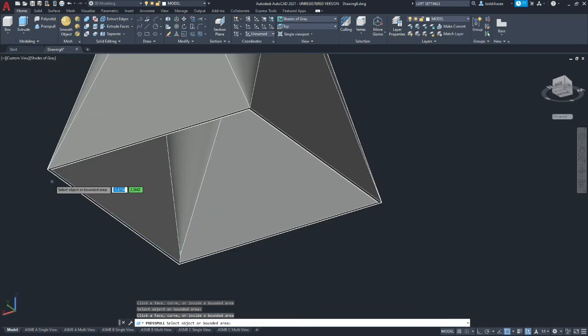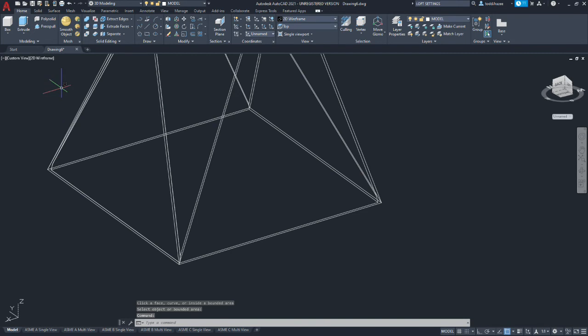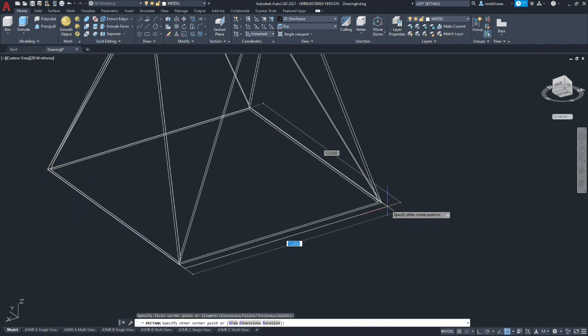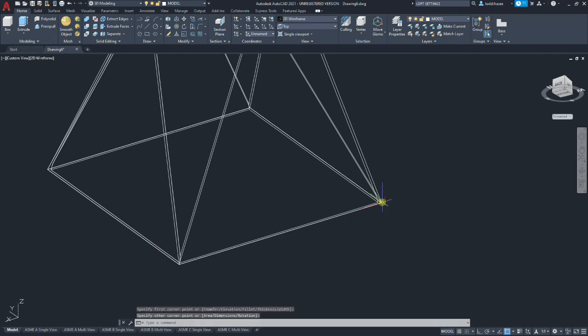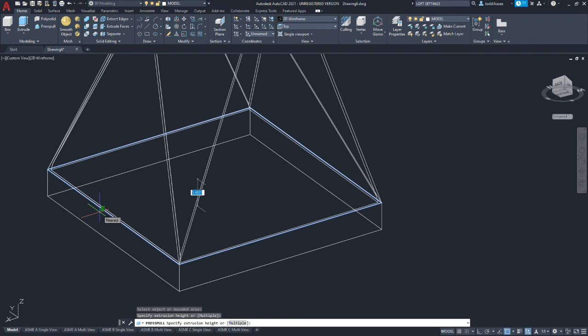So we want to add to the bottom on here. If we press pull on this edge, we're just going to get a thin edge, and we want a solid base because that's what the assignment is calling for. So to do so, I'm going to first switch to wireframe mode. The object snaps seem to work a little better, and we're going to do basically a square from one corner to the opposite extreme corner of the base, and that'll allow us to do press pull, and when we approach that boundary we can select the boundary, and we're going to press pull 2 inches.